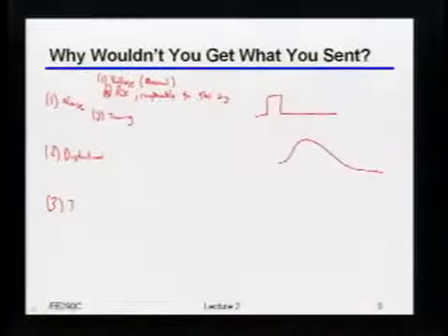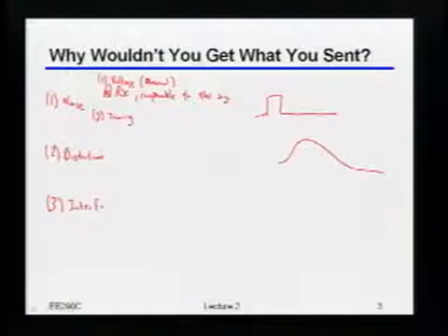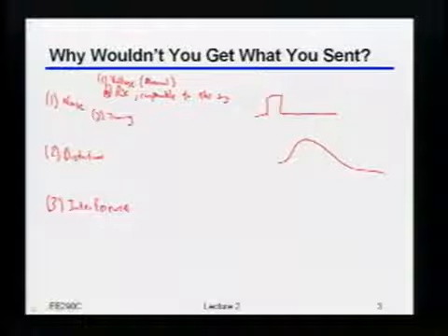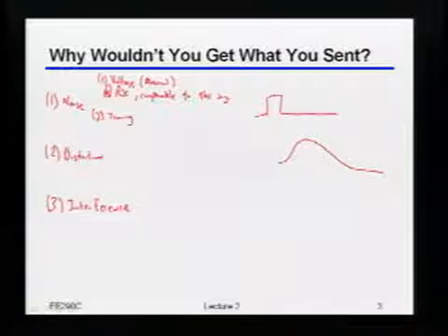Interference. Ah, there we go, interference. So what do you mean by interference? So, you have several links that are probably on the same chip or whatever, very closely located. And if they have a high enough signal, they're going to couple. There we go. So actually, it doesn't necessarily have to do with the size of the signal in terms of how much they couple. Usually that's more, let's say, of a physical thing in terms of the coupling ratio. But certainly how much problem it will cause is strongly dependent upon the amplitudes of the signals, right?